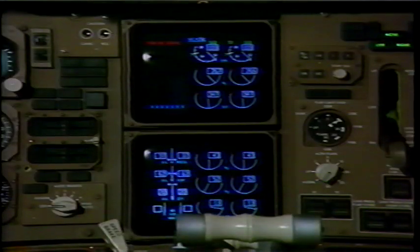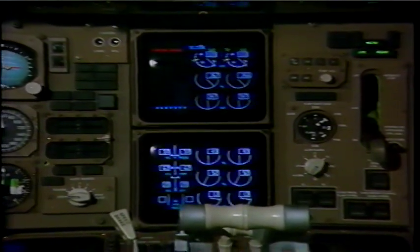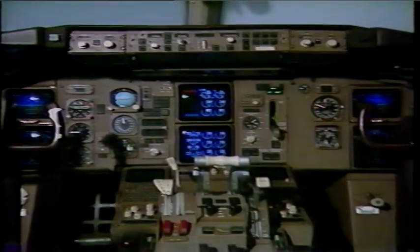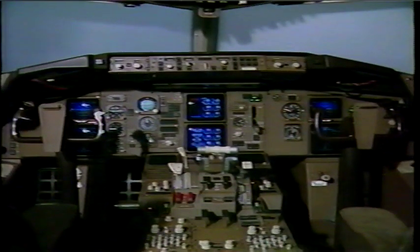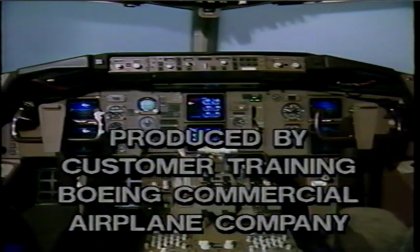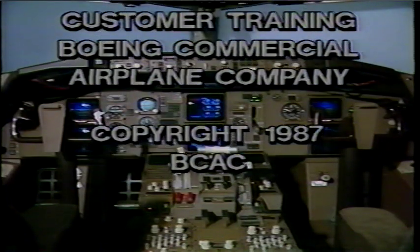This module has been an introduction to the operation of the maintenance display functions of EICAS. We have covered the display of system parameters in real-time, auto, and manual event modes. We have described the recording and erasing of events and exceedances, and discussed the configuration MCDP and test pages, their function and operation. This concludes the overview of the EICAS maintenance pages for the Boeing 757 equipped with the Rolls-Royce RB211 535E4 engine.